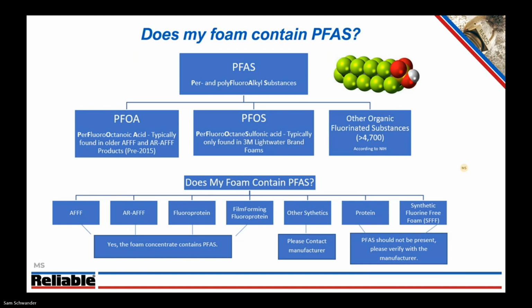The other synthetics group, you're going to want to ask the manufacturer, but for the most part, those don't contain any PFAS. But it's best to reach out to the manufacturer to ensure that it's coming from their mouth, not my mouth. Protein foam, this is just basic protein foam, not film-forming protein foam, not fluoroprotein foam, just regular protein foam. And then synthetic fluorine-free foams. PFAS should not be present, but it's always best to verify with the manufacturer that that is the case.